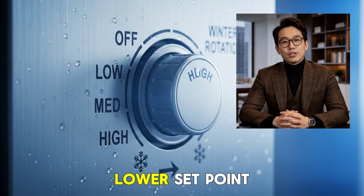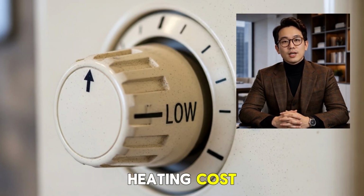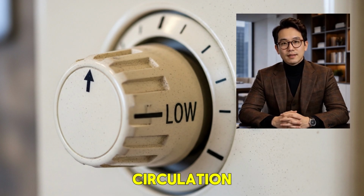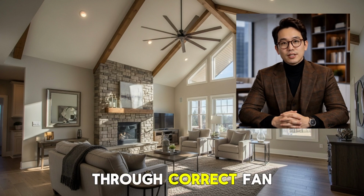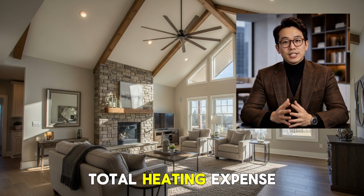The combination of lower set point and improved circulation maintains identical comfort at significantly reduced heating cost. A home normally heated to 72 degrees can feel equally comfortable at 70 with proper air circulation. That 2-degree reduction saves 10 to 15% on heating costs immediately. Add another 10 to 15% from eliminating stratification through correct fan operation. Combined savings reach 20 to 30% of total heating expense.